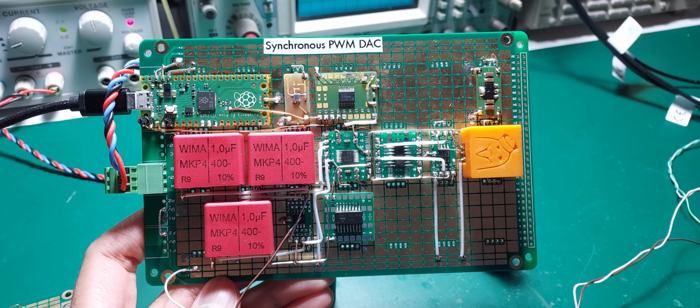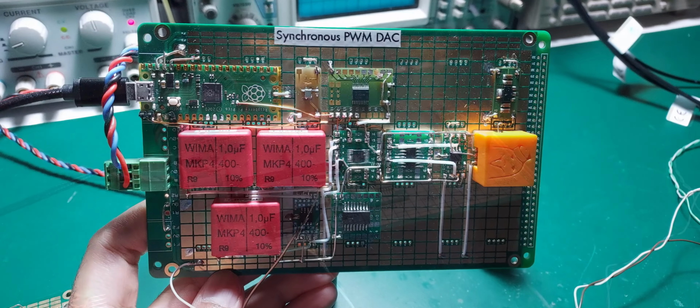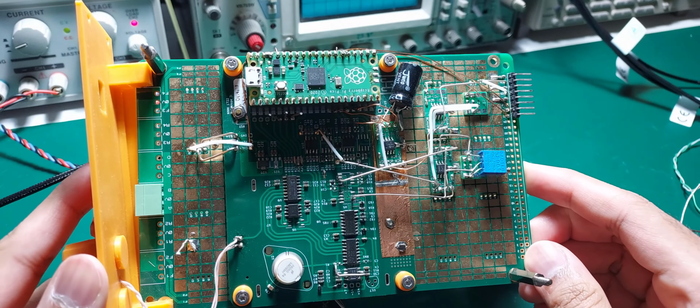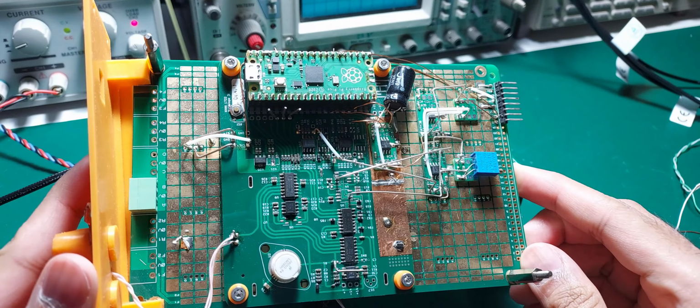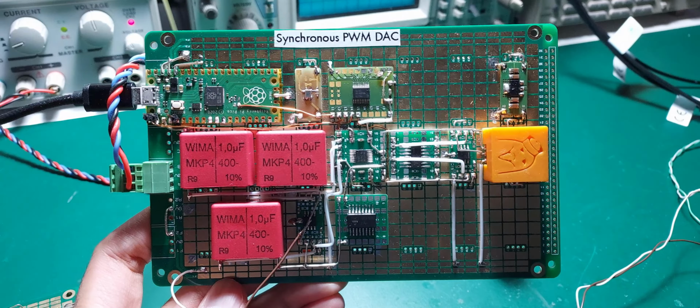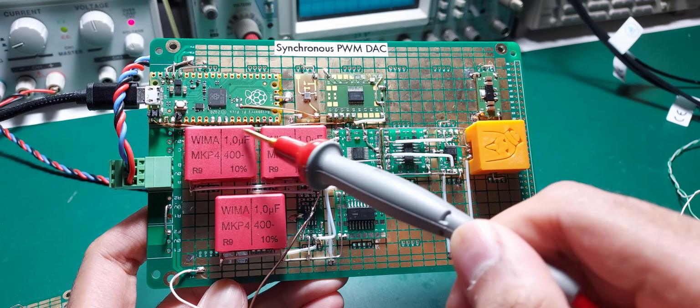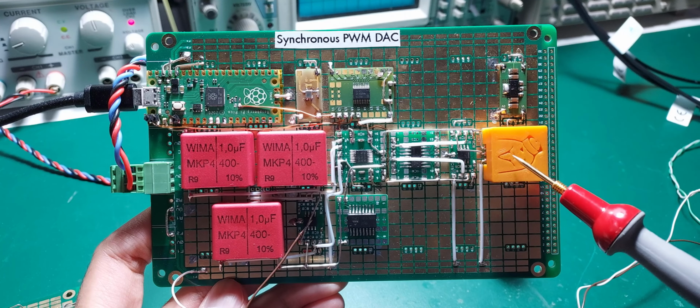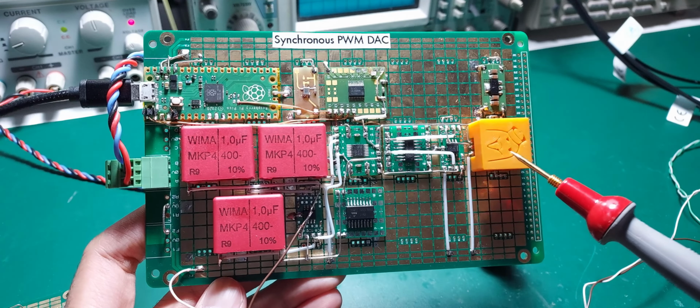The finished product looks good, even if I say so myself. I've had problems with projects looking good but not working well, but hopefully this one will be different, right? The circuit is essentially the same as before, except for the larger capacitors in all positions. Also on board is the TL1963 fast response LDO, which I discovered in the last video.